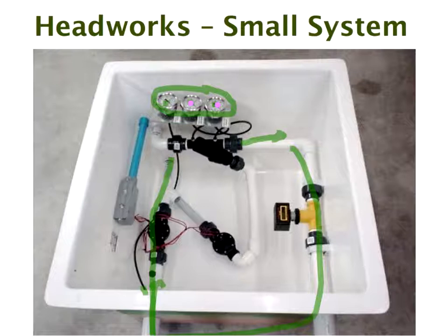Do you really need this while you've got a flow meter? Well, I don't suppose it does any harm. You can look at that very quickly without having to look at the flow meter, but it is also redundant to some degree in this particular case. If you don't have a flow meter, then it's very useful, because if the pressure drop is less than expected, then there's a leak somewhere, and if the pressure drop is higher than expected, then there's a blockage somewhere. That gives you that signal straight away.